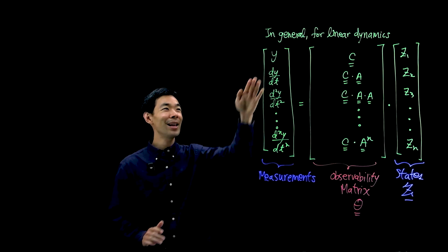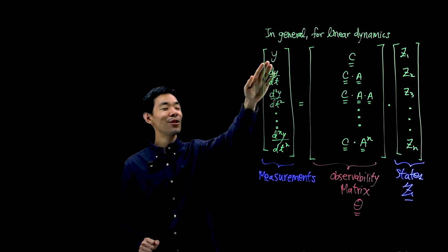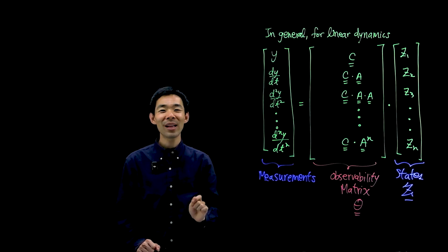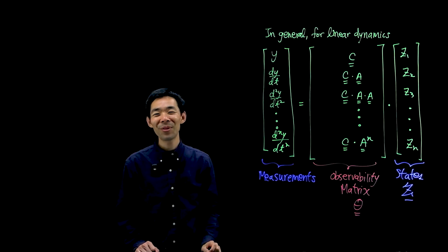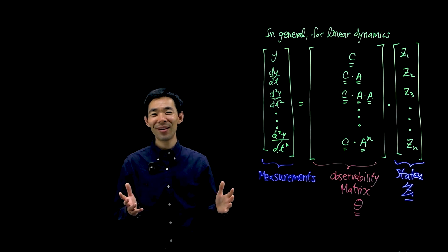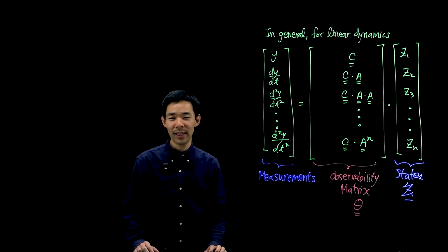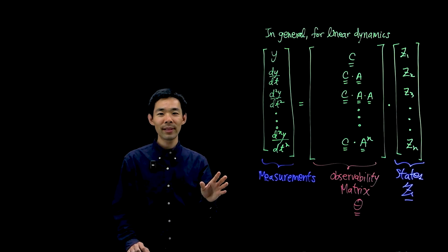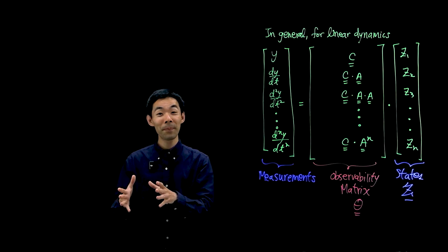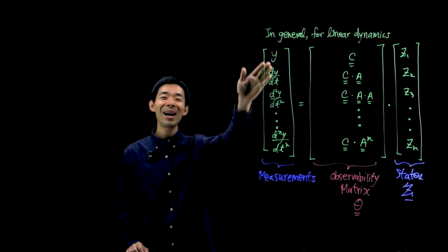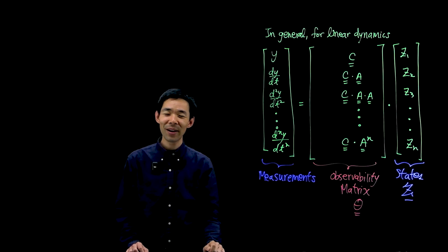Then you can just take n pictures of your temperature. That way you can get n time derivatives of your temperature measurement. Then you can uniquely determine n variables in your entire state. And that's a very powerful thing, and this is called observability. Even though you have measurements and unmeasured states, those unmeasured states are observable based upon embedding or time delay embedding of one of your measured states. And this is a very important concept.